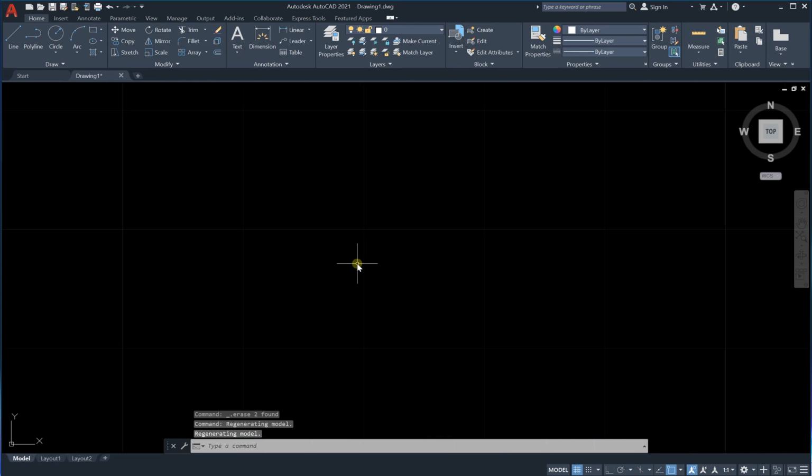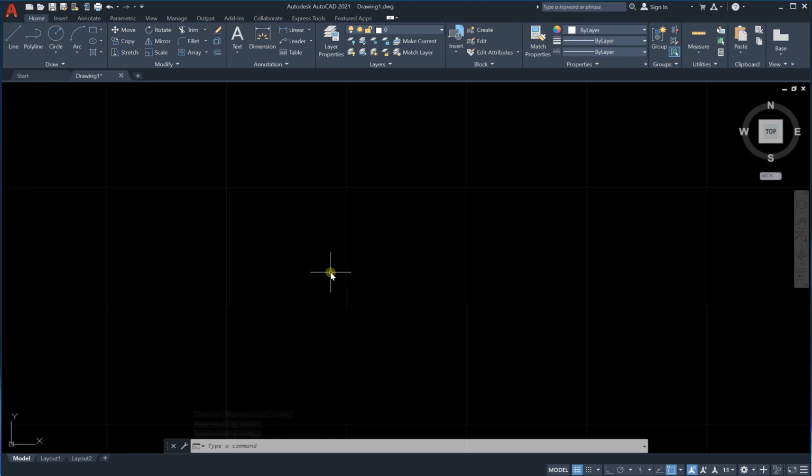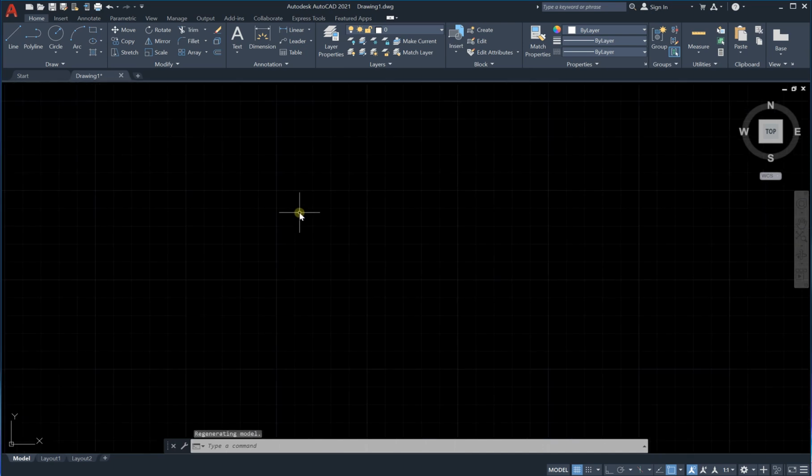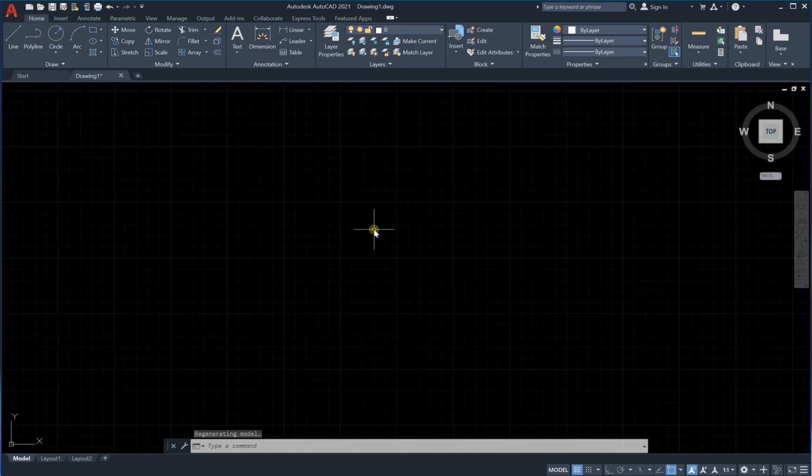Another thing that we would like to discuss in this lesson is the extension lines or construction lines or constructing lines, whatever it is. So how can I do them? You will understand right now. Simply type XL, which is extended line, and we have many options. Okay, so let's start with the first option, which is clicking using the mouse.